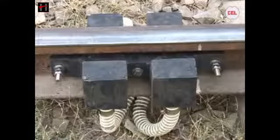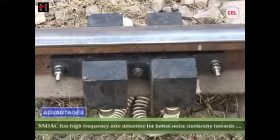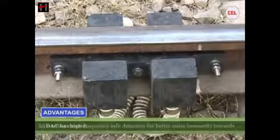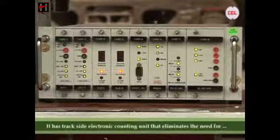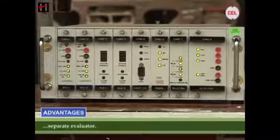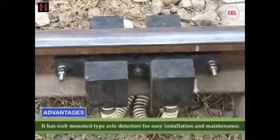The main advantages of single section digital axle counter system over analog axle counters are: the SSDAC uses high frequency axle detectors, that is 21 kHz and 23 kHz, for higher noise immunity to traction current. It has a track side electronic counting unit that eliminates the need for a separate evaluator. It has web mounted type axle detectors for easy installation and maintenance.